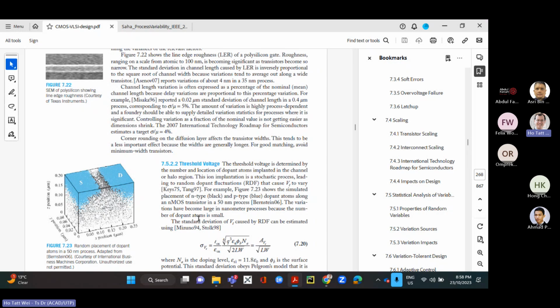Of course, statistical distribution is just the way we think about it. Every single transistor will have its own threshold voltage, and it doesn't change; it's fixed. But if you want to think about the effect on the circuit, it's easier for us to model it as a statistical distribution, that this circuit has a variation of threshold voltages, and the threshold voltage will be about a mean with a certain standard deviation or certain variance.